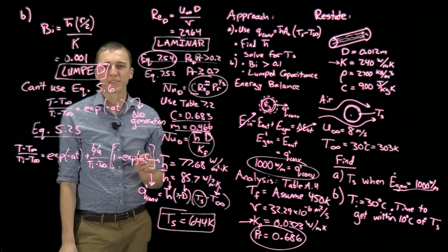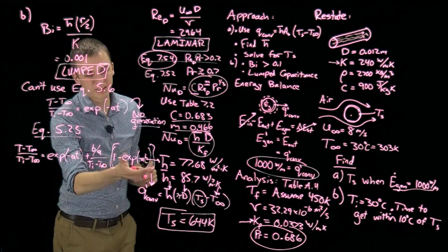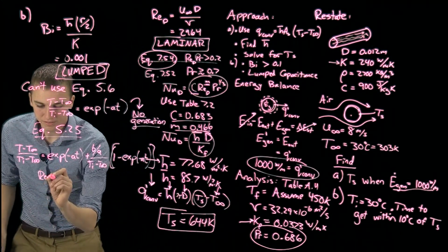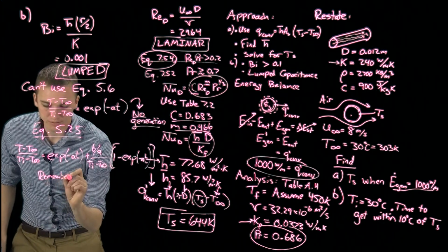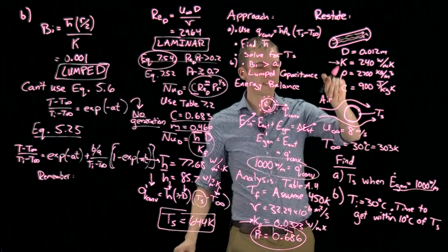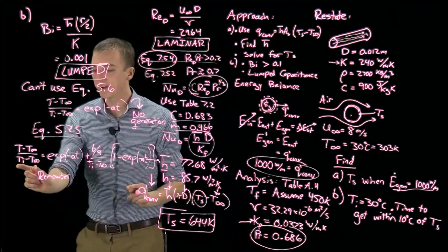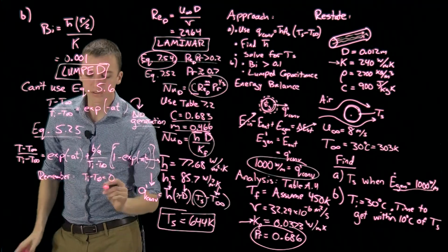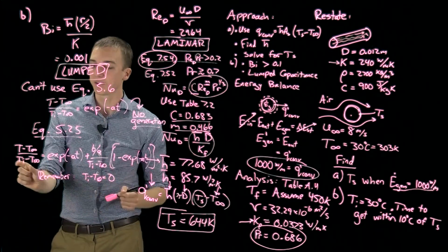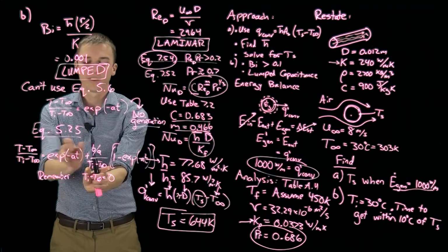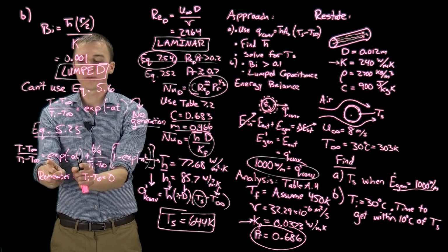We're almost done. Okay, this seems pretty long, and how are we supposed to solve for t? Well, remember that we're asked to do this for Ti of 30 degrees, but that's also what T infinity is. So Ti minus T infinity is equal to 0, which looks scary since we're dividing by it, but let's multiply both sides, and it will cancel here, and this will then be multiplied by 0.